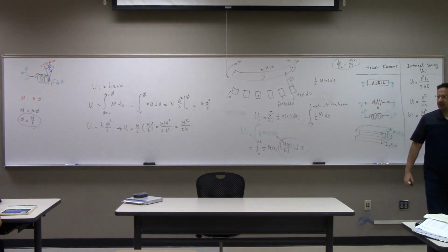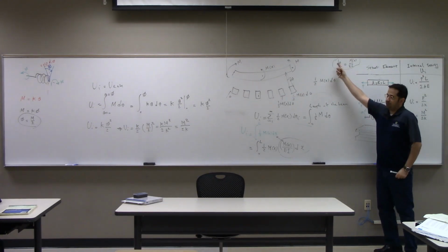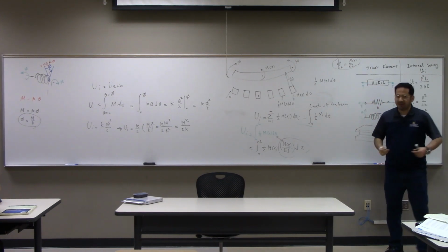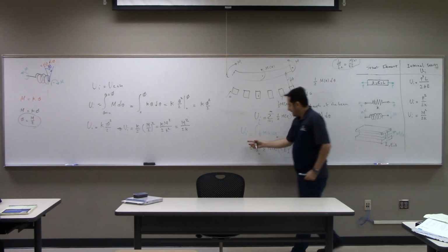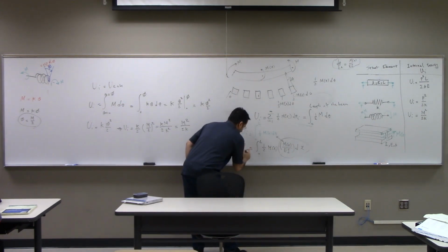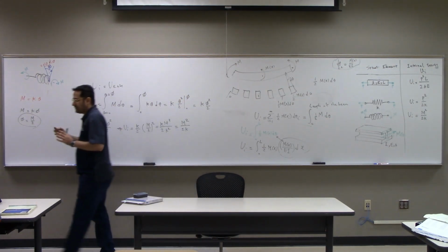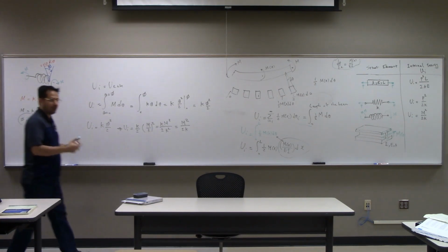You see that? Now those things in the calculus you derive, it shows that it's useful because you always said, well, I solve for the differential d theta, then get M over EI dx. So what's the advantage of that? Well, the advantage is you can plug it here and get the internal energy all in terms of the moment distribution. Why do we do it in terms of moment distribution? Because we already know how to find the moment relation for the entire beam, right? Using Heaviside functions.